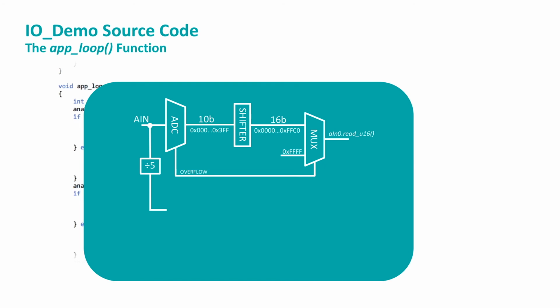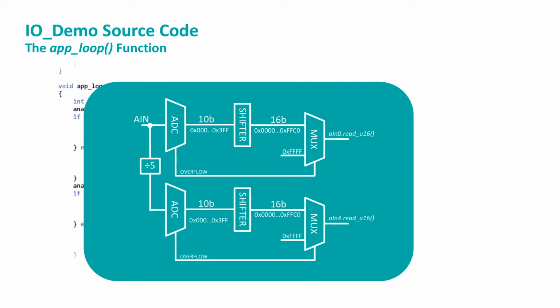The voltage divider reduces the input value by a factor of 5 and presents the divided values for inputs 0 and 1 on ADC channels 4 and 5, respectively. Effectively, this gives the ADC system an overall resolution boost of about 2.5 bits.